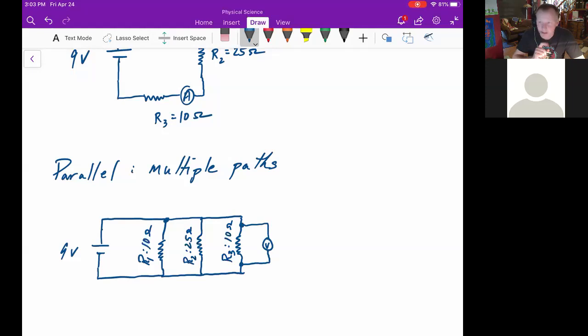Now let's say I wanted to measure the current flowing only through resistor 2 and not the rest of the circuit. That means I've got to put it somewhere in between these 2 points so that any electrons branching off early and going through this circuit wouldn't get counted, and any of them branching off afterwards going through here wouldn't get counted. So they have to be between my first 2 red marks there.